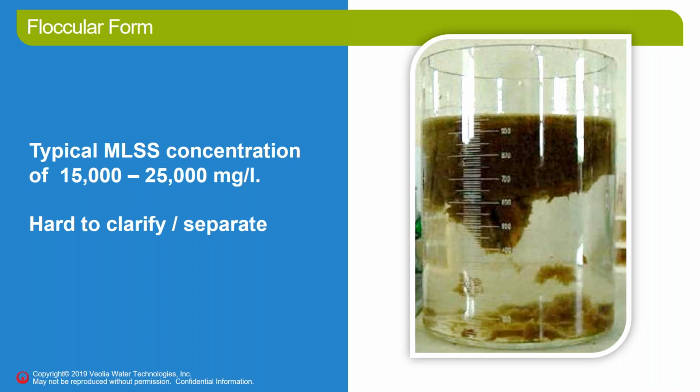If you don't want a lot of solids in your effluent, you would have to add some polymer, some flocculent coagulant, so that it would congeal into a better form, which is actually what's shown in this picture here. That's had some flocculant and coagulant mixed with it, so it's held together, so it does get some separation.